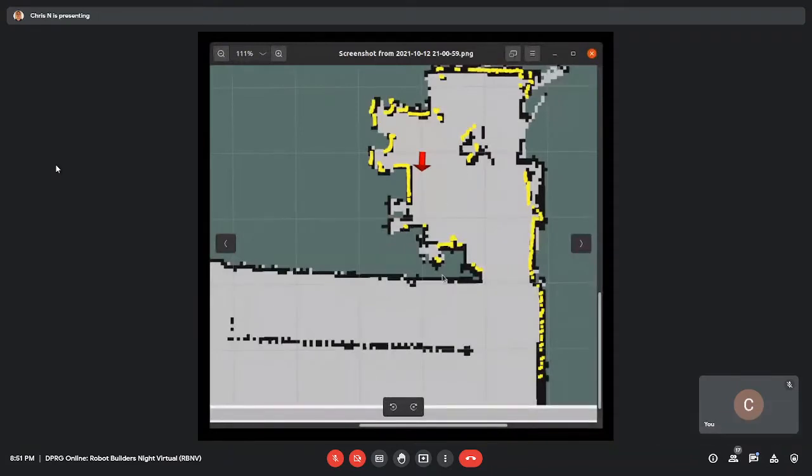So this is now, again, after 5 minutes of driving around, and because I'm doing this with recorded data, and I'll talk about it in a second, it's processing the exact same data, but now it's combining the wheel odometry, IMU, and output from the SLAM module. And the map that it's generating, okay, it's interesting, but focus on where the robot is, right? It's right there again, at the intersection of the two grid lines. So again, that's what the localization is doing for me.